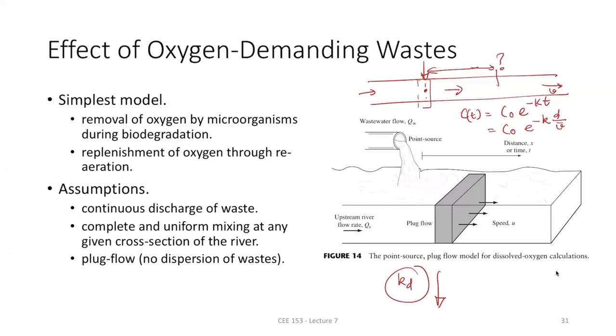So you can write K aeration. The aeration means oxygen is mixing with water and dissolving in water. So that's what it does. It increases the DO concentration. So this is decreased DO concentration. That's one rate. So there are two different rates here. So you have to add both rates in this particular equation and solve it. So let's do that one.